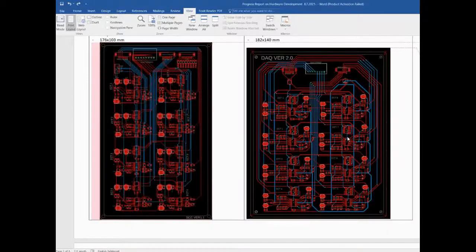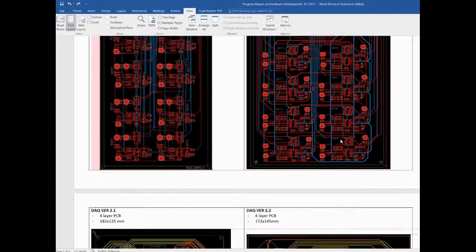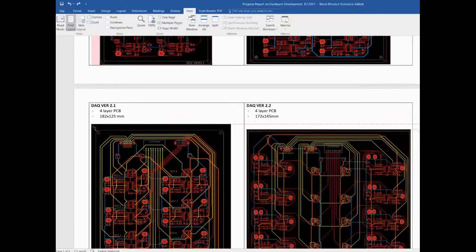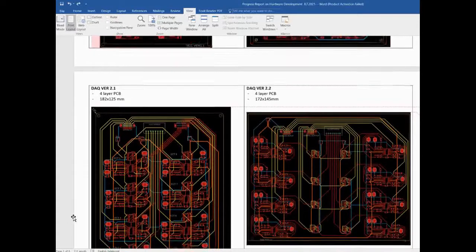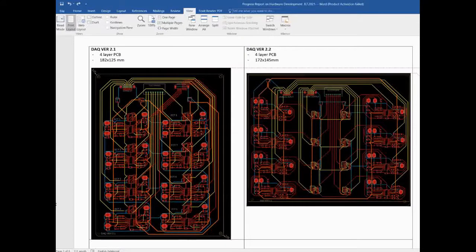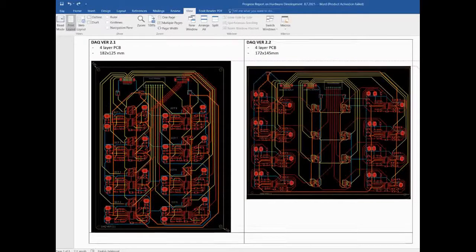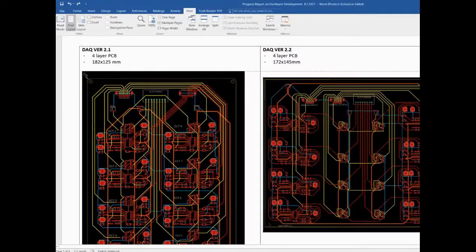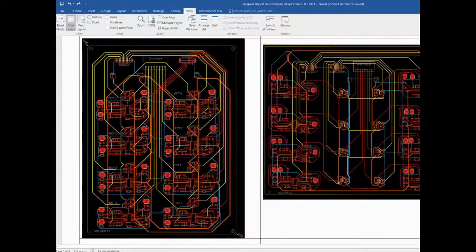So what I've been doing is rearranging the routing, and I try not to route within the components. That's all for this. This is still 2 layers, but when I studied again, the proper design for PCB, if you want to avoid EMI problems, is to use 4-layer PCB, because it dedicates each layer to different traces.